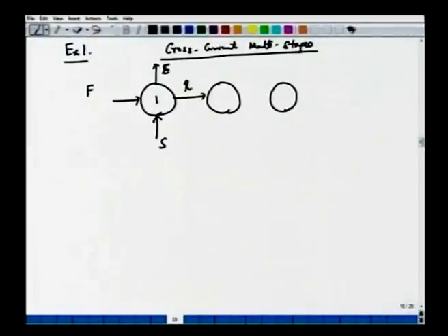So stage 1, this is R1, E1. Take this raffinate to the second stage, bring in a fresh amount of solvent, we have the extract here, treated raffinate R2, bring it in contact with the third stage, again with solvent, and we have this R3 and E3, etc.